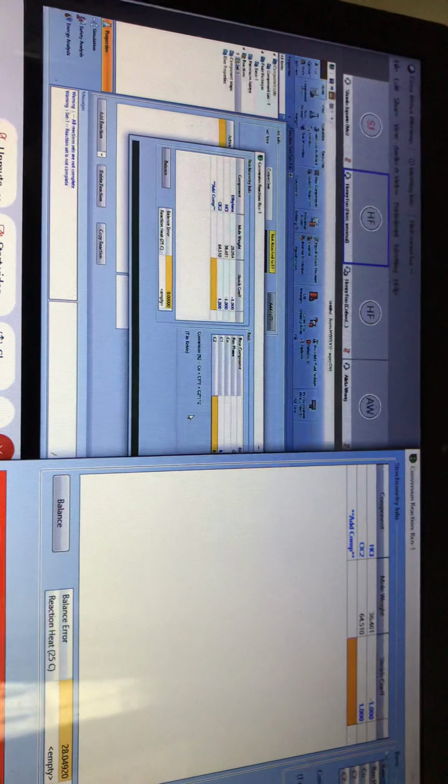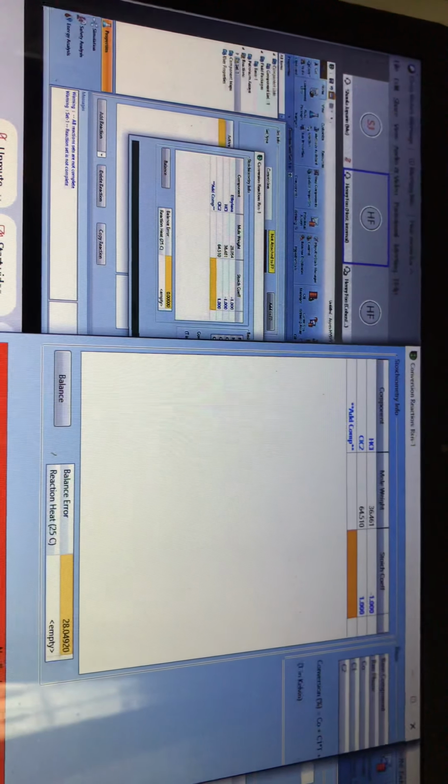Okay. Just now, if you did not type 0 for C1 and C2, or leave them empty, I think by default they should be equal to 0. But to avoid any confusion, it will be better for you to type 0 for C1 and C2 if the question never states the coefficients for C1 and C2. Okay, so there you have it. This is how we define reactions for conversion reactions.